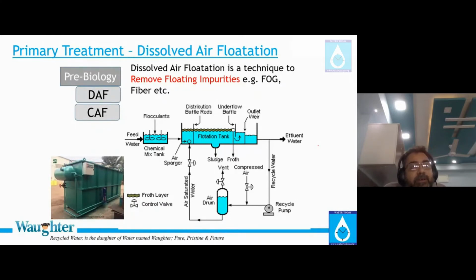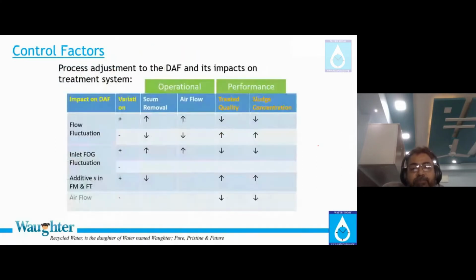So it depends where it is, an industry. So there's nothing called conventional thing. DAF is conventionally not used in sewage treatment. But suppose you decide that you want to do a wastewater treatment plant for a restaurant and park and eatery and all those kinds of facilities, it is better to go for DAF, electrocoagulation and filtration rather than a biological system. I do not say that a biological system won't work. It would. But it is better to go for a DAF kind of technology.